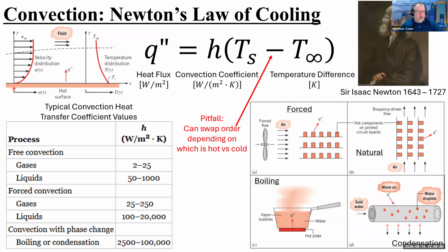So you might remember this one, if you took my class. I love flow over flat plate. This is a prerequisite to airfoil design for fixed wing aircraft. I'm an airplane guy, so flow over flat plate is near and dear to my heart. If you remember the final exam, we had a question about boundary layer development and the Blasius solution on the fluids final. So here's the velocity profile for flow over flat plate.